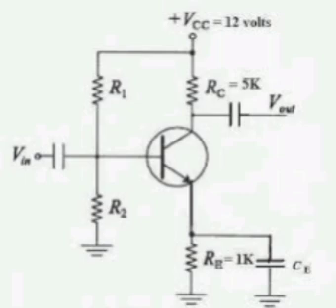What are the two functions of commutator in DC machines? The commutator in DC machines has multiple functions, including converting AC to DC in a DC generator. The commutator converts alternating current into DC. In a DC motor, the commutator converts DC to AC, collecting and supplying current. The commutator collects current from the armature conductor and supplies it to the load using brushes, ensuring one directional current. The commutator ensures that the current from the generator always flows in one direction, providing unidirectional torque. In a DC motor, the commutator also provides unidirectional torque.